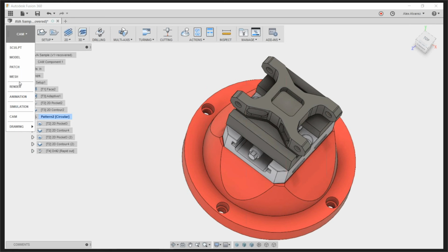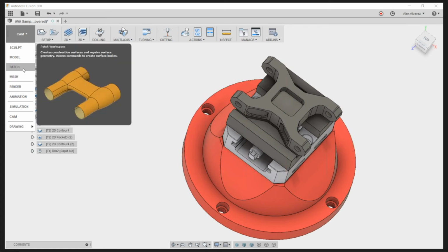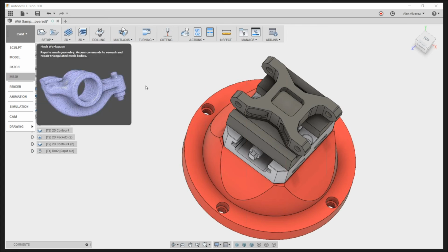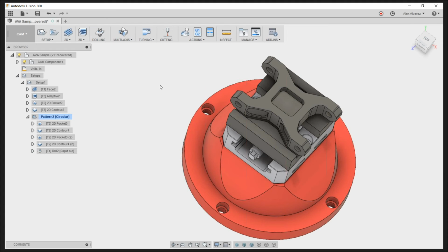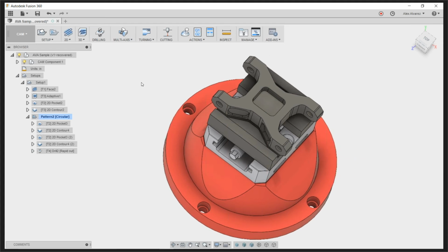So what you can do is create your sheet metal part, create a flat pattern for it, and then jump over to your CAM environment and create maybe water jet or plasma toolpaths for that sheet metal part. Yep. So you'll use HSM, or Fusion, for some of the cutting aspects. But creating those bends, creating that bent part, and generating flat patterns so you can send those DXFs to your water jets or plasma cutters, you do that in a separate environment.